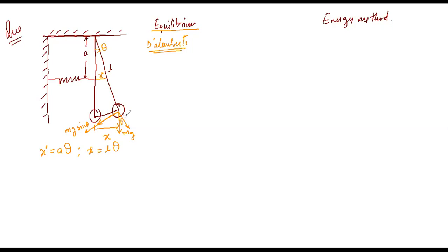Then your equation should be, now at this particular position a spring force will act, which you will call k x dash, right? K x dash. Now when we displace this position, an inertia force will act in the opposite direction, because this body is moving in this particular direction. Your inertia force is I theta double dot, right?